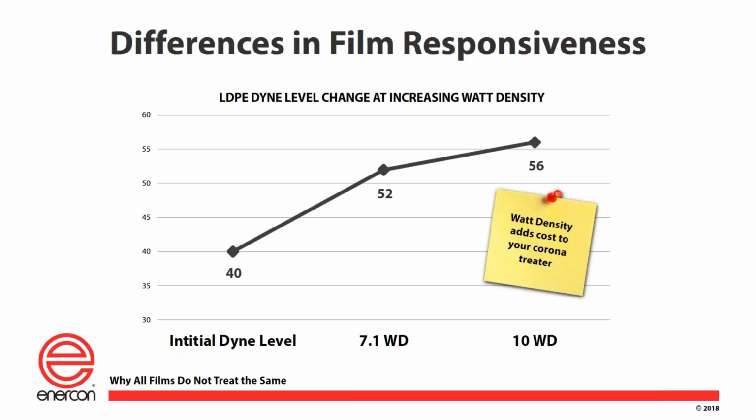to get them to understand that, first of all, the process isn't linear, and there's multiple pieces in the process that doesn't require it to be linear. You know, the ink chemistry doesn't require, in this example, a 56 or 52 dyne number to be successful. And so requiring these giant watt densities, or giant dyne numbers, really, which then in turn may require giant watt densities, really do you a disservice and are not useful in terms of economics or in terms of, you know, best use of capital, or for that matter, a treater of this size, if it's an existing piece of equipment, just trying to find a space for this equipment would be pretty hard to do on an existing asset.